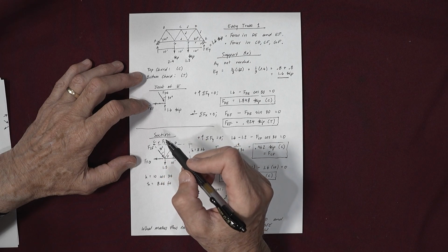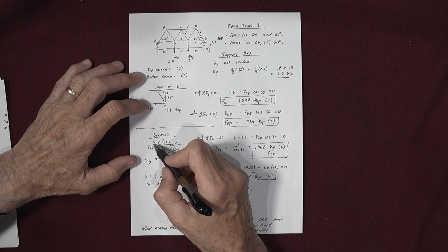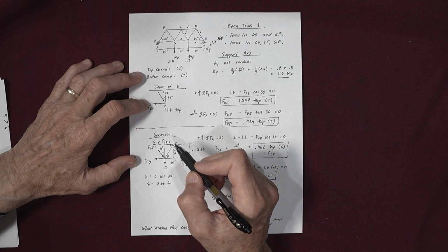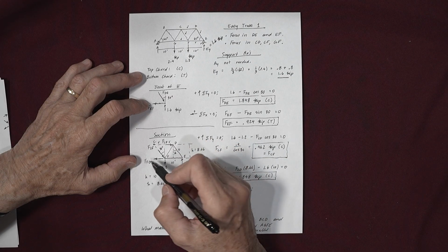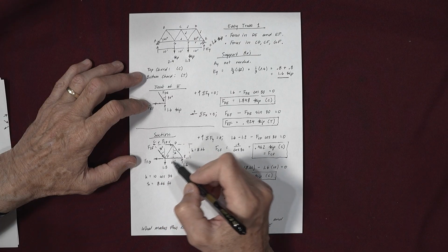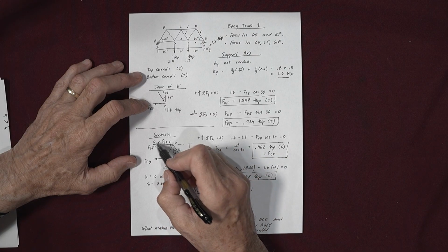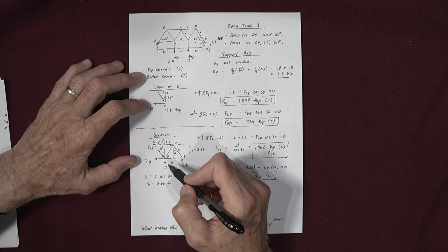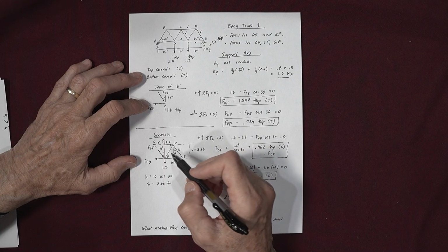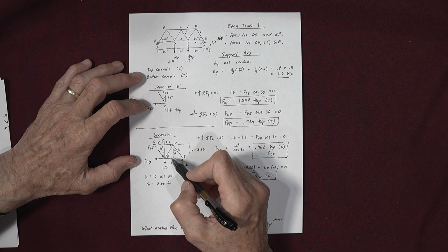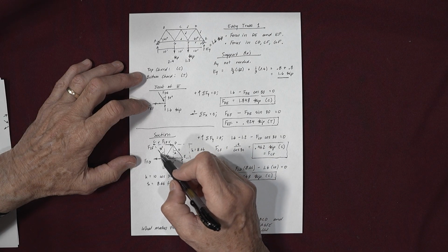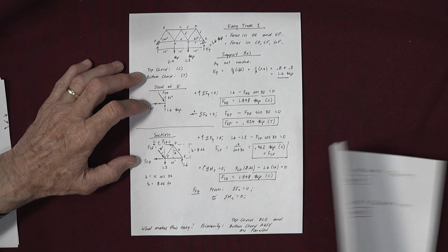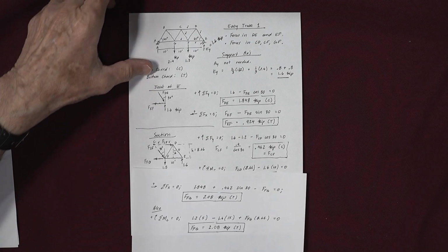They intersect at C. And so if I sum moments about C, it basically removes these two forces from that summation. All I'm left with is FFG, 1.2, and 1.6 in that moment about C. This is a really common method or technique on trusses, where we slide forces along their lines of action and sum moments about the points at which they intersect one another. So let me just show you what those equations look like.